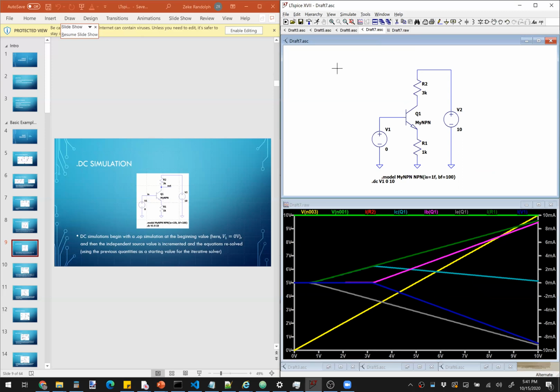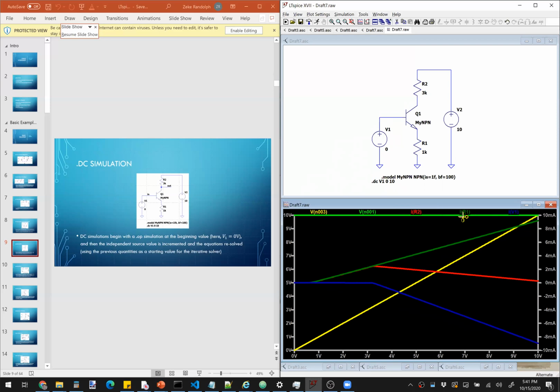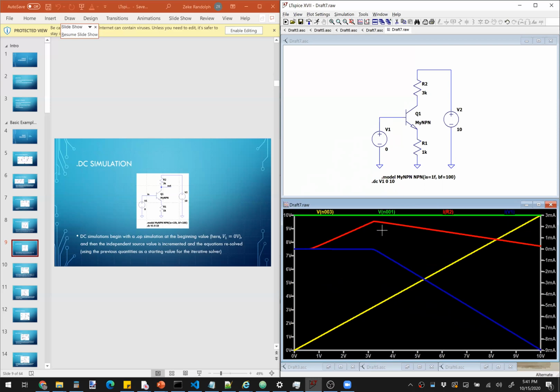Here's something that you'll notice. Whenever I have the schematic selected, it looks like this little mini window is focused. All of the various menus and stuff are associated with schematic editing. If I click on the waveform viewer, then these menu items change. Okay, and so now they are representative of what tools are necessary to change the waveforms. So I could begin deleting waveforms. So here's the cut tool, which is F5, or in my case, it's X. And I can begin deleting waveforms and just start all that stuff, or right-click to get out of it.